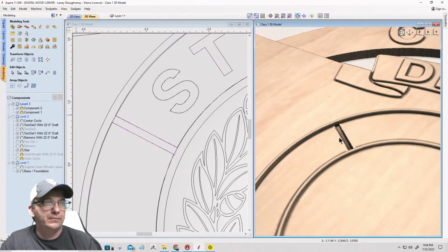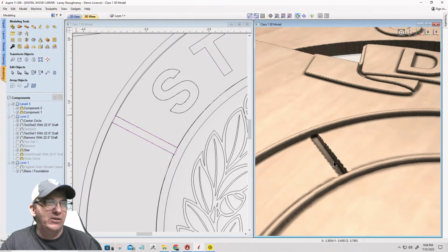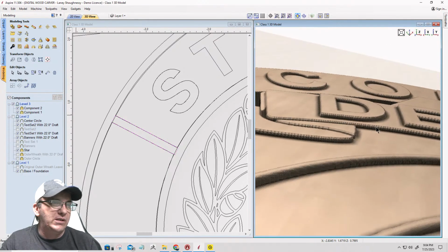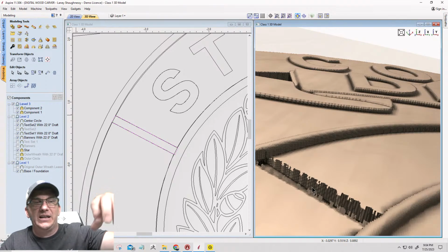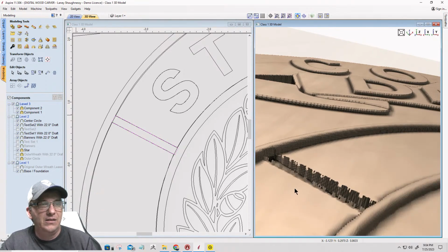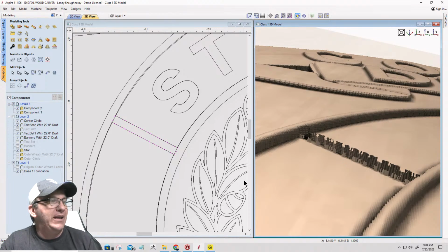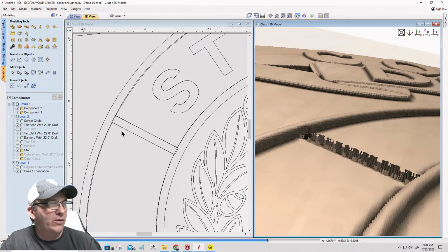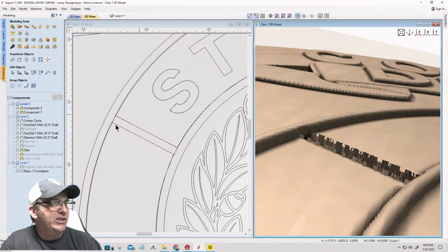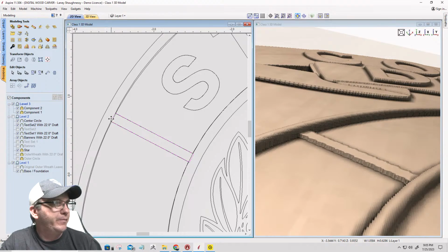Okay. You will see that that material is removed, but you see those fibers and everything? That's because there's still some of that component remaining there, so my rectangle wasn't quite wide enough. Let's do a really quick undo, and let's make the vector a little bit wider, so make sure it overlaps these two edges a little bit more. So let's go into node editing.